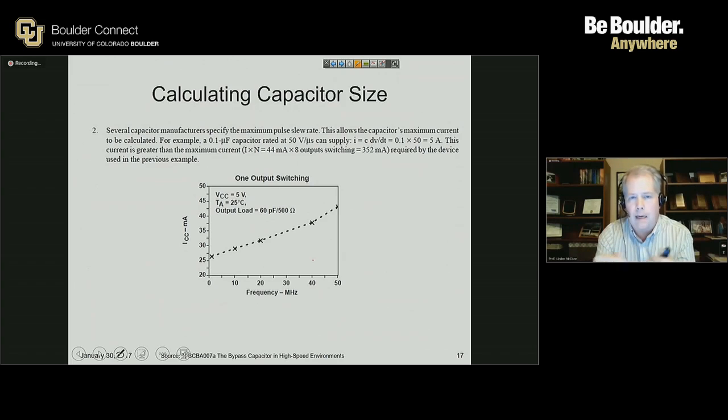my integrated circuit, and it's coming through the leads of this capacitor, and that capacitor has effective series resistance that is significant, I'm actually going to get some voltage drop between the capacitor voltage and the pin of the chip that I'm delivering to. And in addition, I'm going to get some heat loss. What is the power associated with the current that's flowing through that effective series resistance? It's I squared R. We know that from Ohm's law, the voltage drop is IR, and then that times the current of I gives us I squared R losses that are in the capacitor itself.